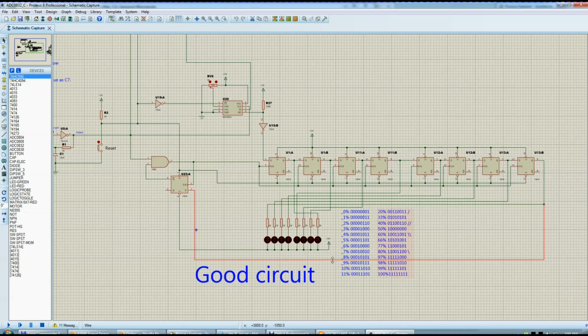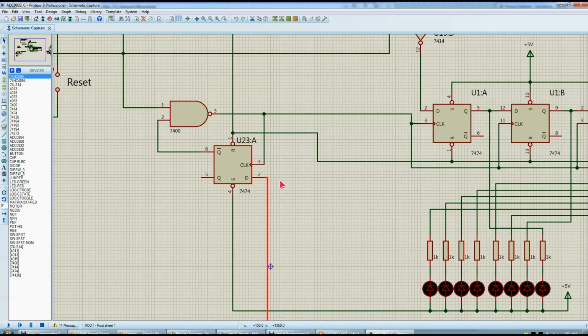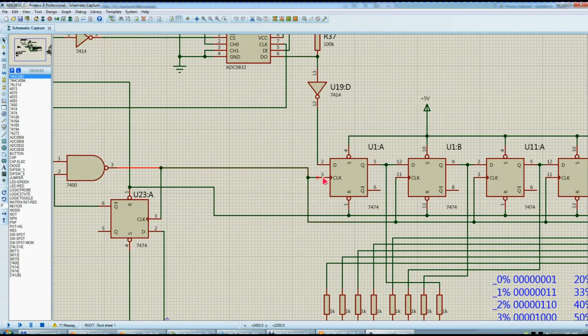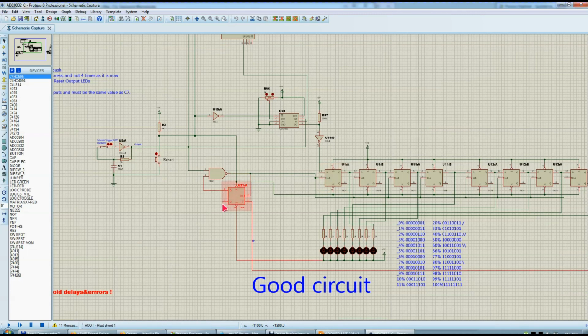And when this last bit is used, it will send the same signal here to this flip-flop, and because this is flipping all the time, this will count very, very fast. When the NOT Q from this flip-flop is activated, it will catch one activation from the timer that I have on this pin, and it will clock only once all the outputs, including this one, and switch it to off.